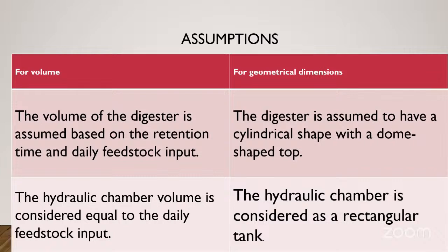You can make two more assumptions: that the hydraulic chamber volume is considered equal to the daily feedstock input, and finally, that the hydraulic chamber is considered a rectangular tank.